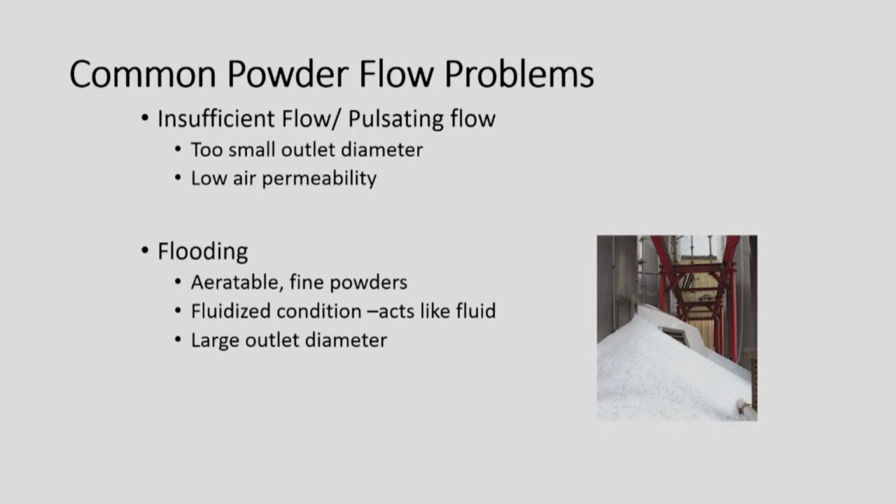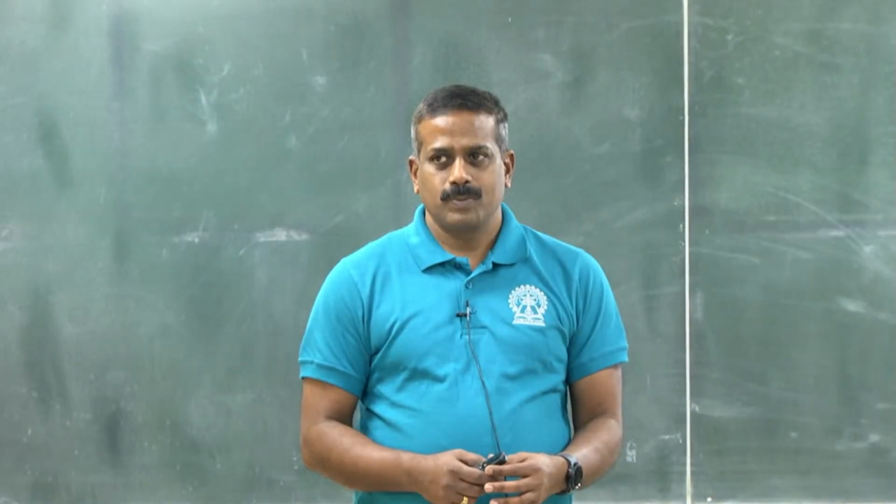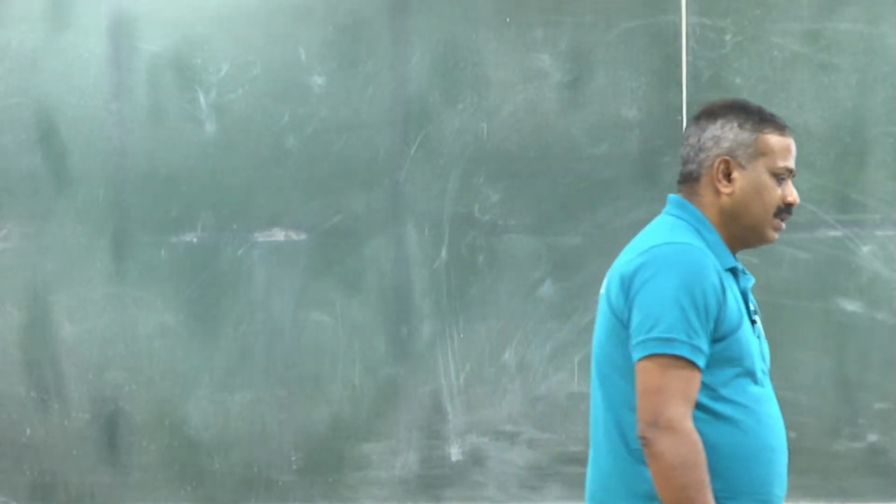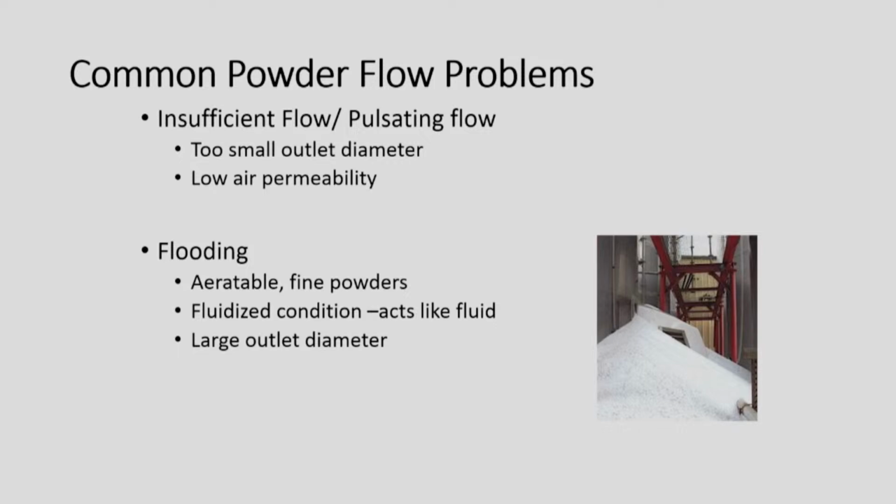Or why and how does air help with flow? For example, if you go to a large bulk wheat flour milling facility that manufactures tons of wheat flour, when they unload wheat flour it doesn't flow very well, since it's small particles, right? So they put an additional pipe to supply air through the bottom so that it flows smoothly and easily. So how does air help with flow?